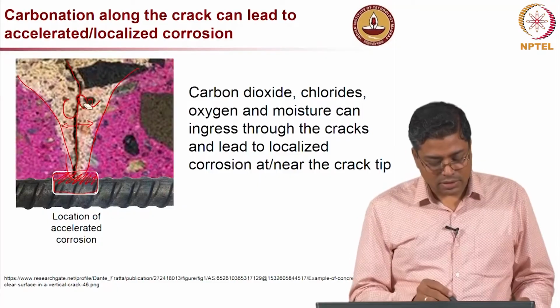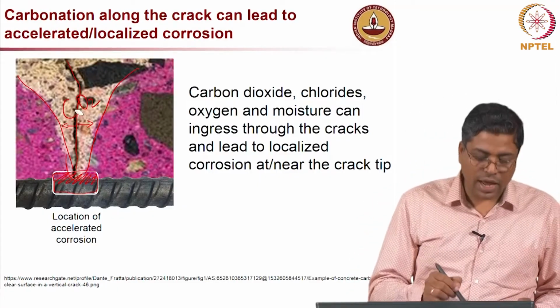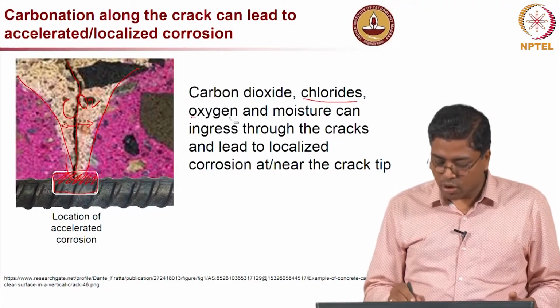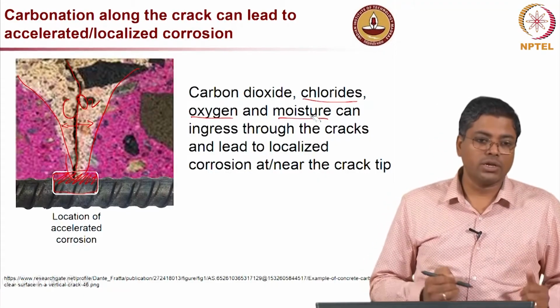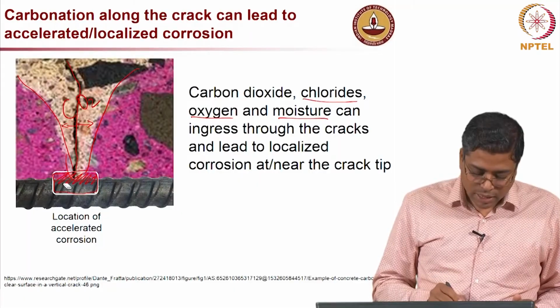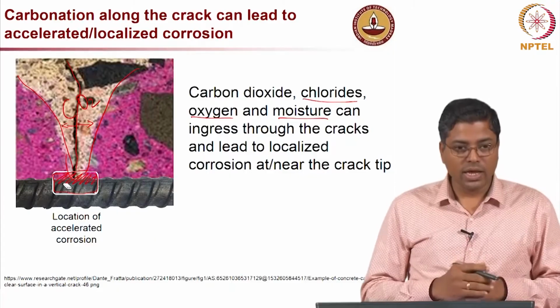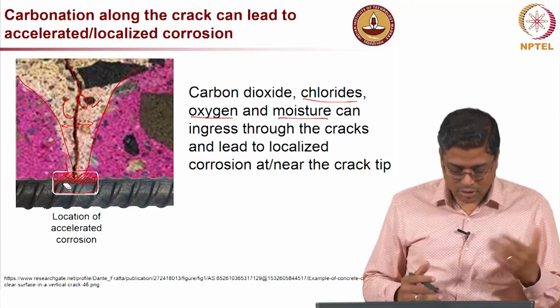Similar is the case, it is not just carbon dioxide. If there is a crack, chlorides, oxygen and moisture can all penetrate through these cracks, and they will attack the steel in a very localized manner, which is very dangerous when you talk about structural behavior.